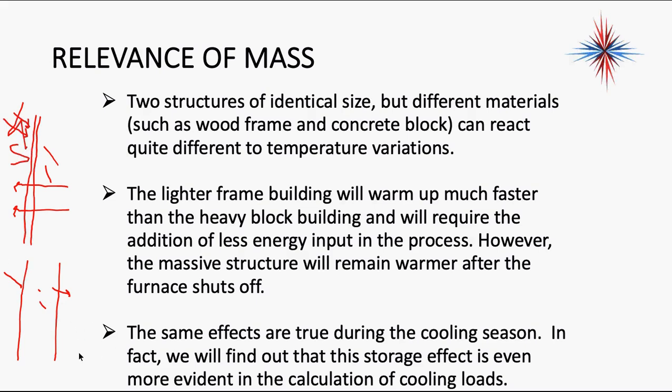We might have 2 hours of direct sunlight before the heat starts penetrating that concrete. However, once this wall warms up, the sun goes down, I am still going to be putting off heat into this indoor environment for 2 to 3 hours after the sun moves off that area.